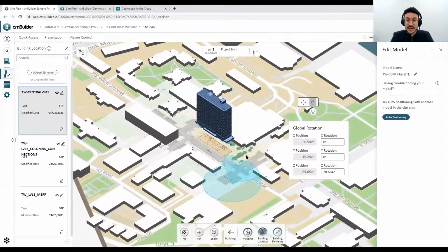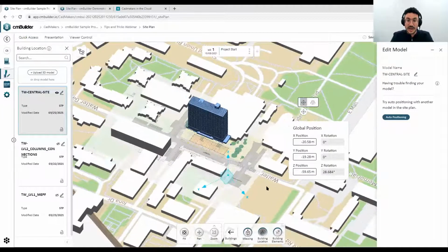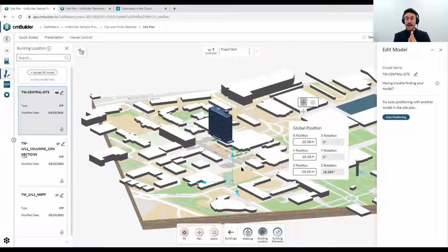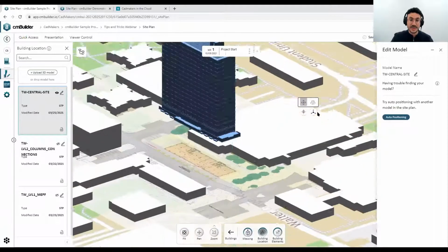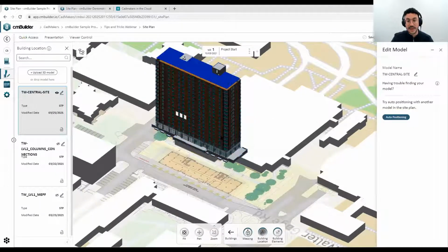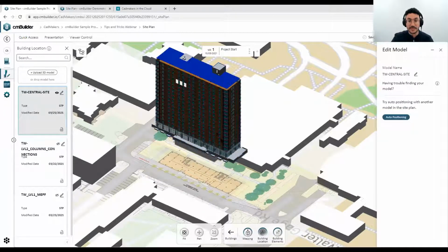And what you're seeing over here, that the handles are over here way below the model, is because we are looking at the part origin. So this model has its own origin, like I mentioned before, and these handles will be snapped to that part origin. But if I want to change where these handles are located, I can change this to my local origin. So local origin will basically track wherever I click and place my handles in the click position, right?